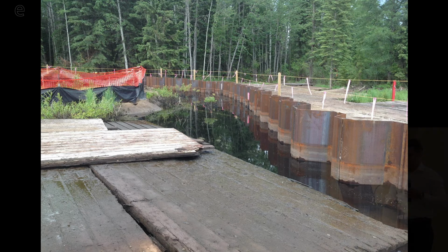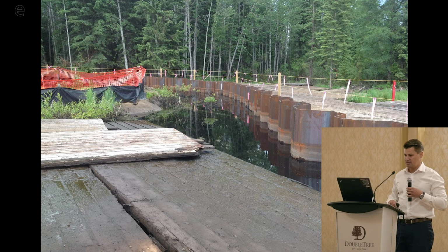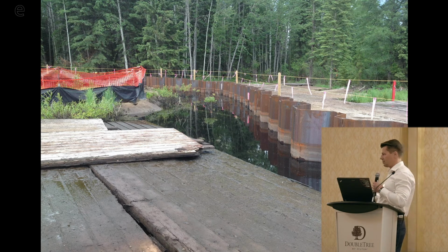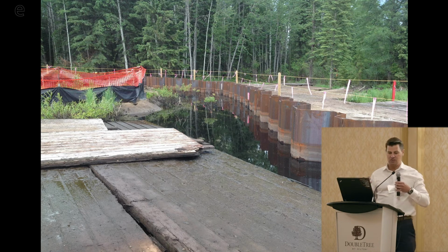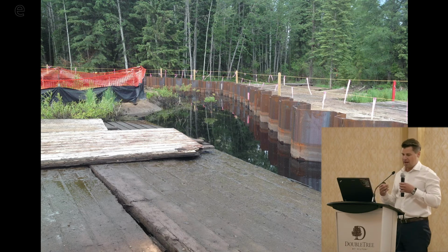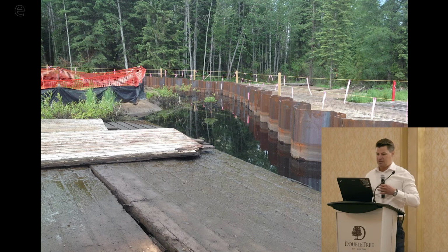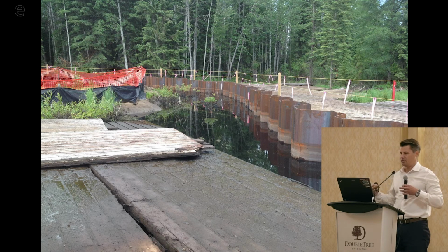On the picture above that is an example of steel sheet piling that you would drive down into the ground. You can also use geosynthetic liners or slurry walls that can be a mixture of bentonite grout, cement, and maybe sand, and engineered clay where you can backfill and compact to a moisture and compaction density standard. Basically, you're just trying to decrease the permeability to prevent ongoing migration of the free product.